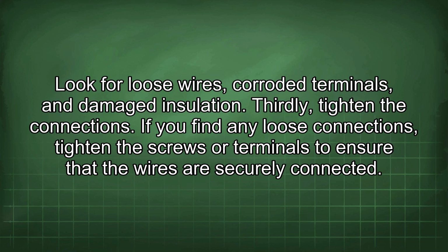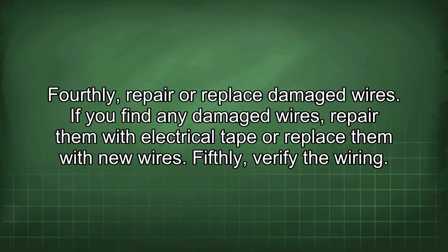Look for loose wires, corroded terminals, and damaged insulation. Thirdly, tighten the connections. If you find any loose connections, tighten the screws or terminals to ensure that the wires are securely connected. Fourthly, repair or replace damaged wires. If you find any damaged wires, repair them with electrical tape or replace them with new wires.